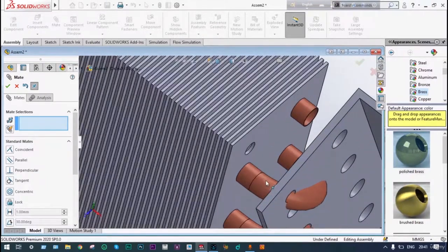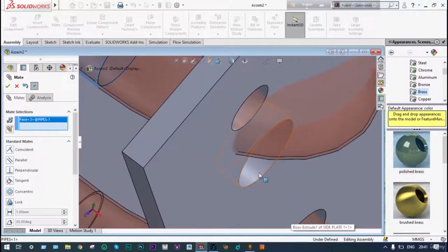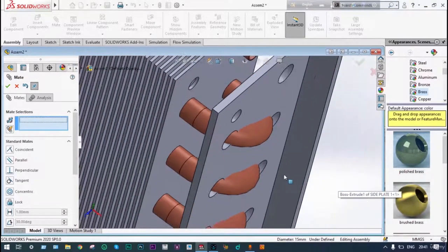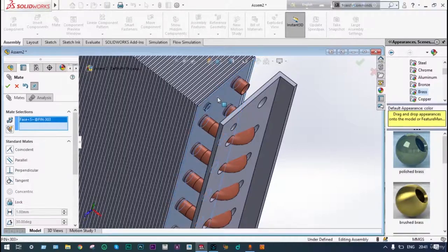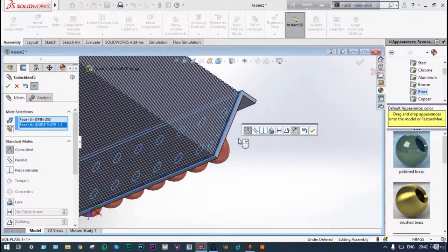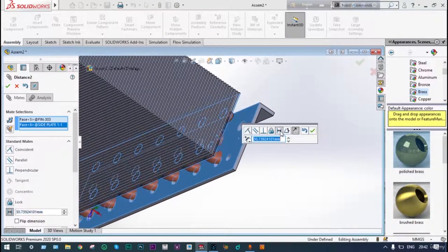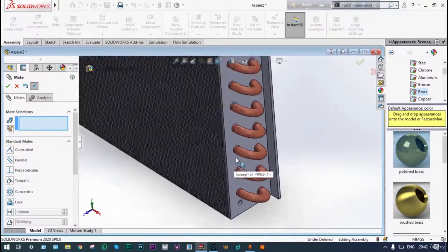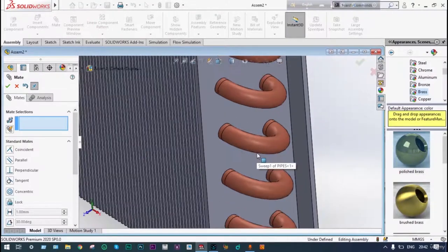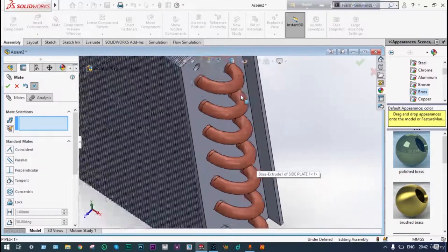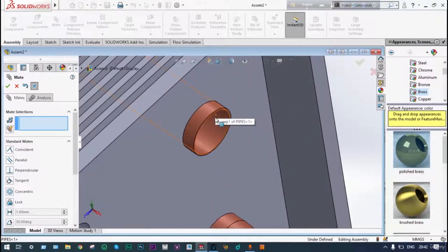Okay, the other one. Again, the second one you can select. This location should be meeting with this hole. Two constraints are done. Now the third one, we can provide the distance between them. Here to this back side, it will be 2 millimeter. The distance will be 2 millimeter. We can provide. Green check. It is done. You can feel that another could be provided, right? No issues, we can provide anytime. This is the end part.